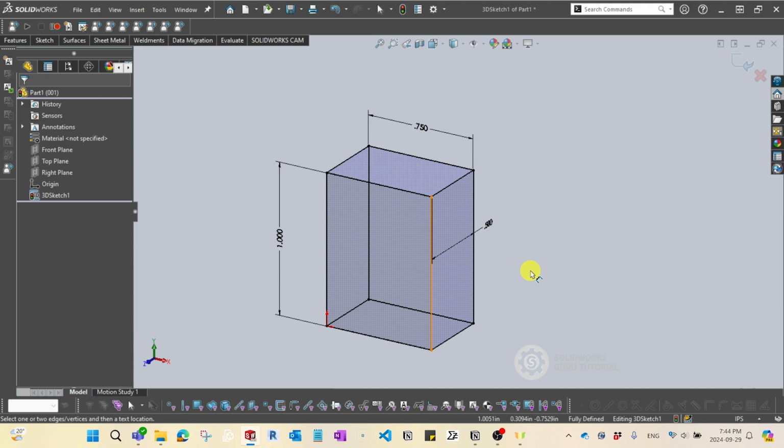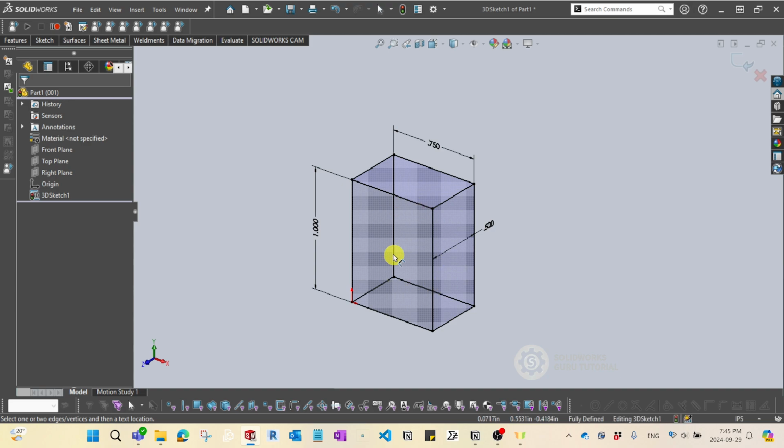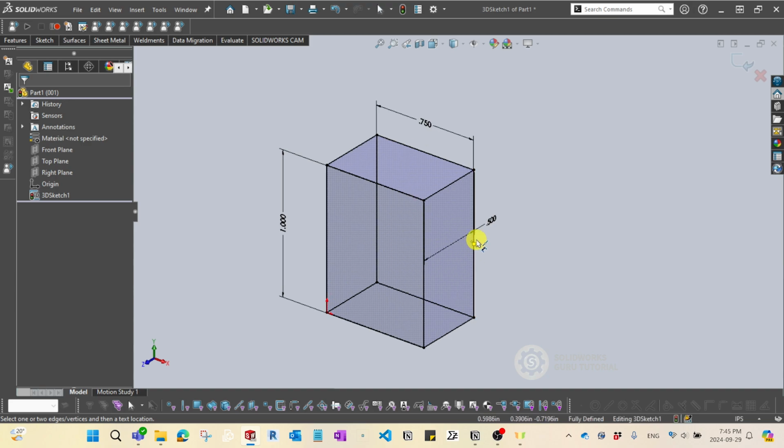So you can keep changing the origin point that you draw the 3D sketch from. You have to utilize Tab to keep changing the direction of the arrow, so then you can draw that line. It's a little bit more advanced for sure compared to 2D, but once you get familiar with this, you'll have a lot of opportunities.